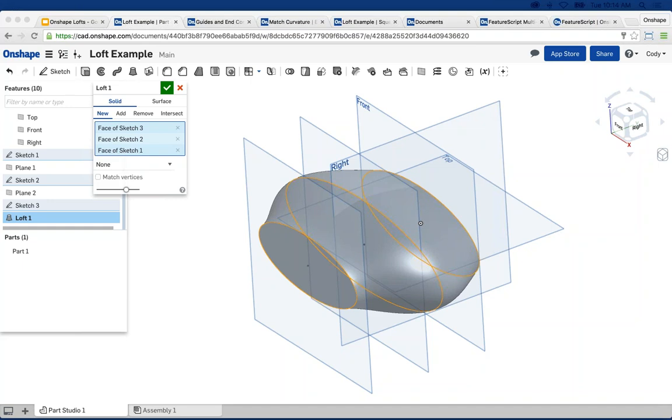Quick questions, a few questions. Why is it a curved guide, not a straight one? When you select more than one profile, if you select 2 profiles, it's going to give you a smooth transition between the shapes, not a straight transition between the shapes. That's the idea behind it, is it gives you a smooth transition between curvature, not a sharp transition, I would say. Forgive me if I'm misunderstanding that question.